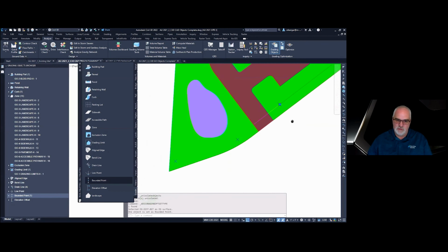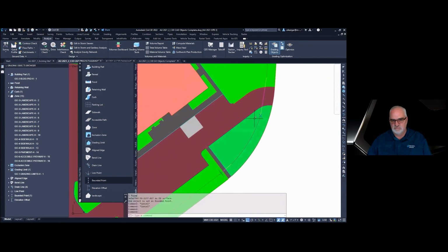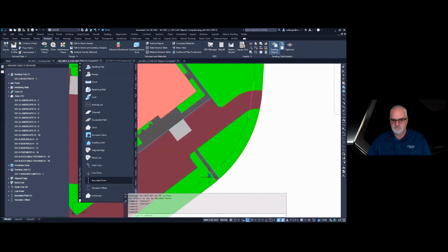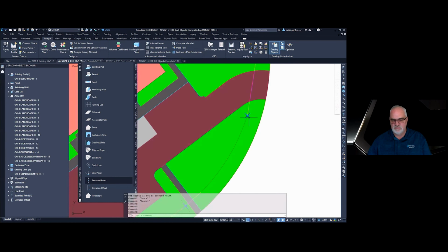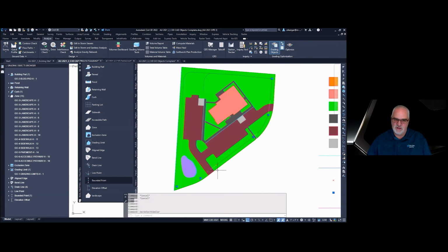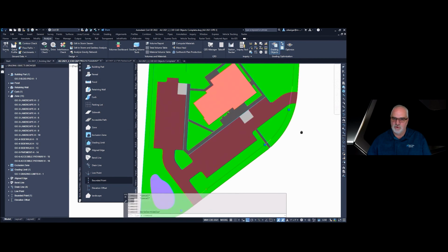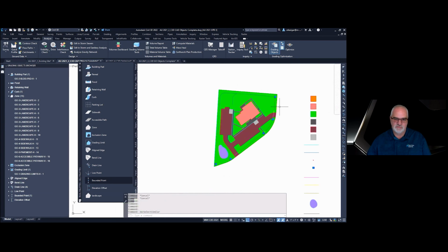And then you have low points. So I have, this is a low point, this is a low point. There's a low point right here, here. So every place I want that ditch to flow to, I'm telling the drain line here, and then there's a low point, drain line, low point, drain line, low point, okay?